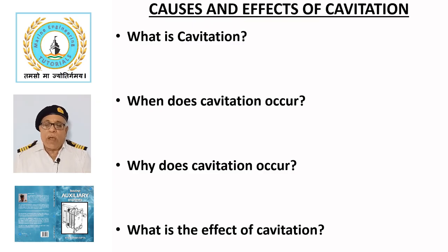Cavitation creates pitting marks on the impeller vanes and volute casing inner wall, which increases resistance to flow, resulting in reduced pump efficiency, premature failure of the bearings, and mechanical seal.